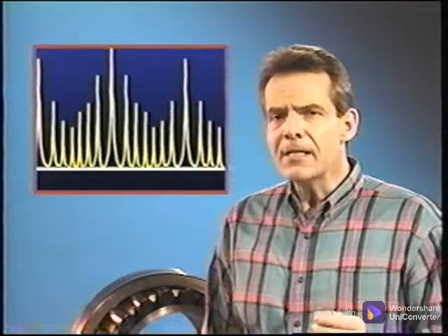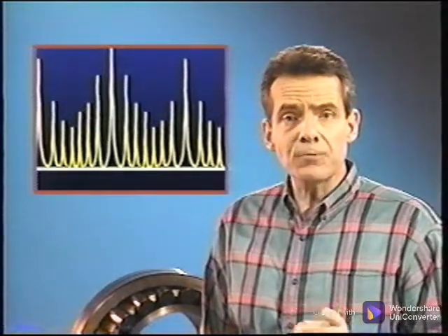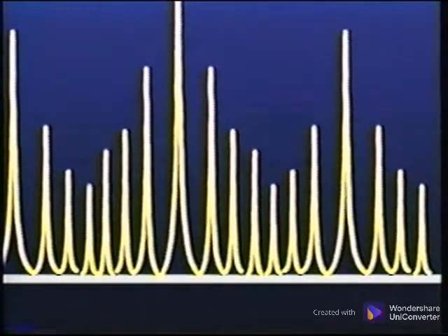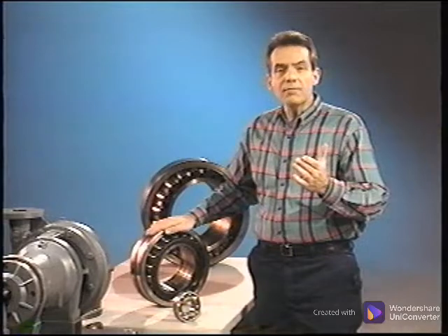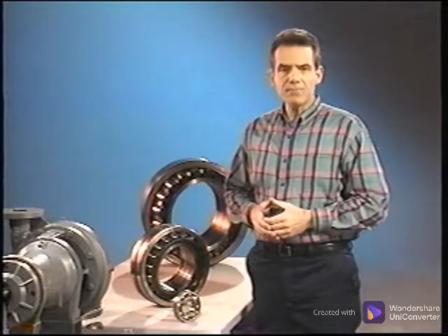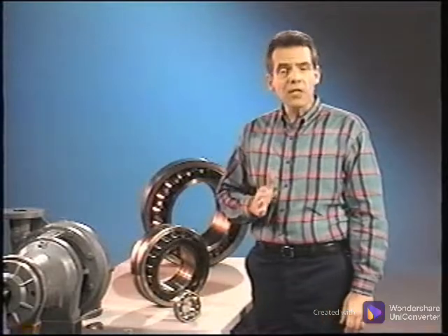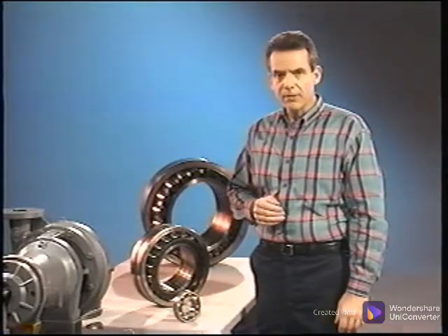Let's look at the setup required to collect data that ideally maximizes your ability to capture bearing degradation. The maximum frequency should be set depending on the bearing and the speed which it is turning. Race defects will show up in the higher frequencies first and could be as high as the number of rolling elements times the calculated race defect frequency.